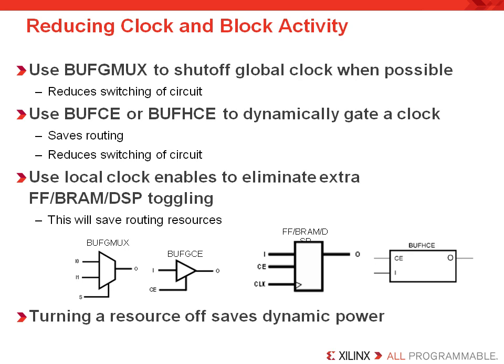You should also take full advantage of the BUFG mux, BUFG clock enable, and the BUFH clock enable to gate an entire clock domain for power reduction. Now this can be done to pause the clock in an entire clock region if you'd like. Likewise, for applications that only pause the clock on small areas of the design, use the clock enable pin of the FPGA register for that functionality.